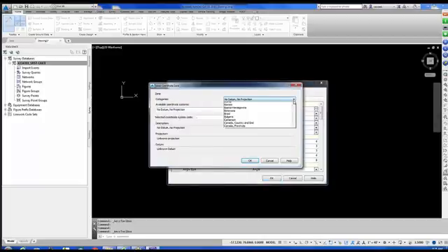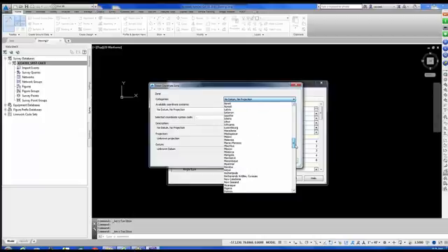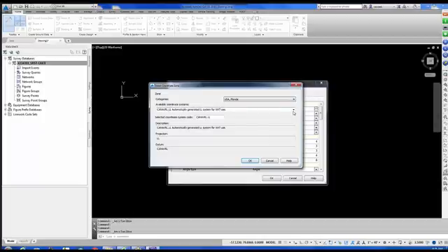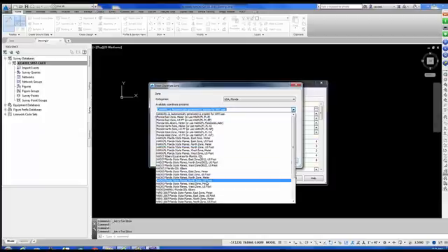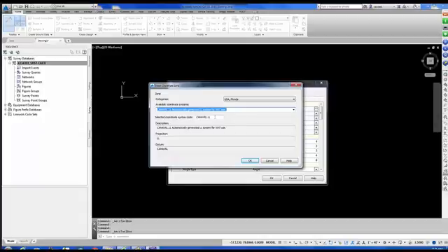Under the category, I can pick the down arrow, slide down the list, and pick USA, Florida. And then under the available coordinate systems, I can pick the down arrow and say NAD 83, State Plane, North Zone, US foot. Or if I know the coordinate system, I can just type in FL83-NF and basically shortcut the whole process. Once you start working with the 3 coordinate systems that we use in the state of Florida, it's probably just faster to type it in. But either way, it gets you to the same spot.